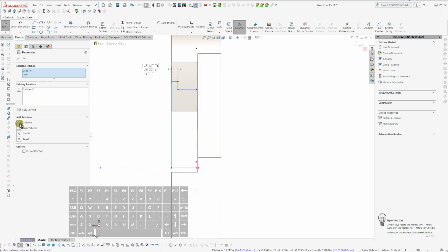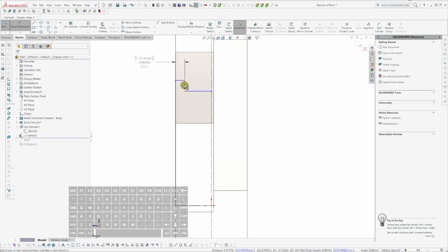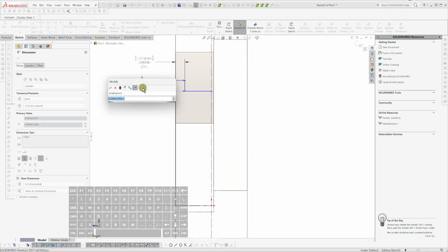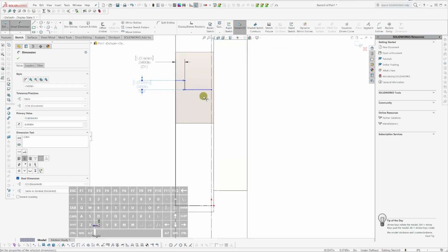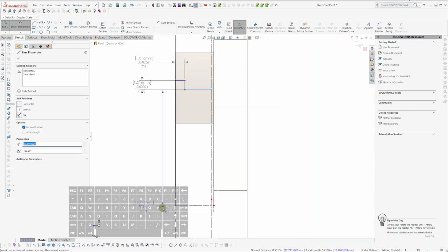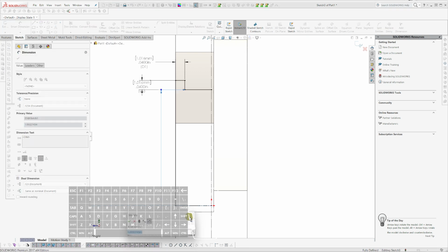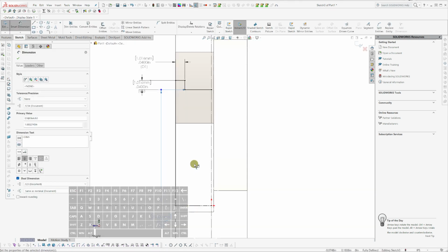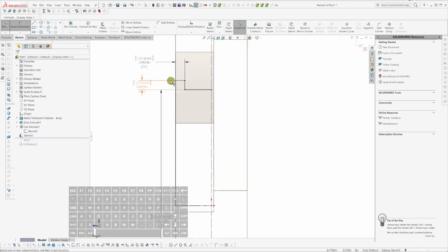And then I'm going to make this collinear without edge. Did I not? I missed the button. Okay. And let's give this overhang. We don't need much. Let's just call it another millimeter is fine. And let's call this diameter inch. That should be fine. And then I am going to mirror.